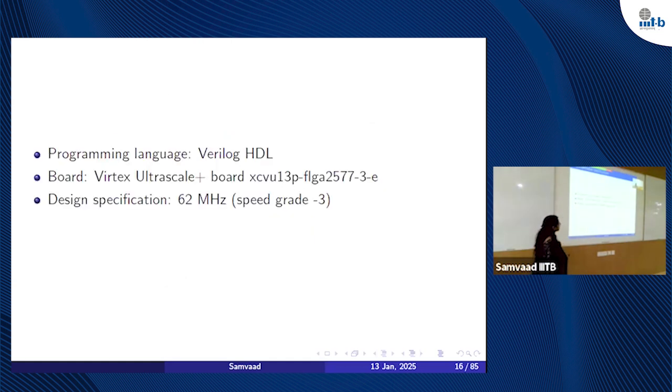This design was written in Verilog HDL, and it was implemented using the Virtex UltraScale Plus board, the recent board at that time. And the frequency that I got is 62 megahertz, the maximum operating frequency, based on the critical path.